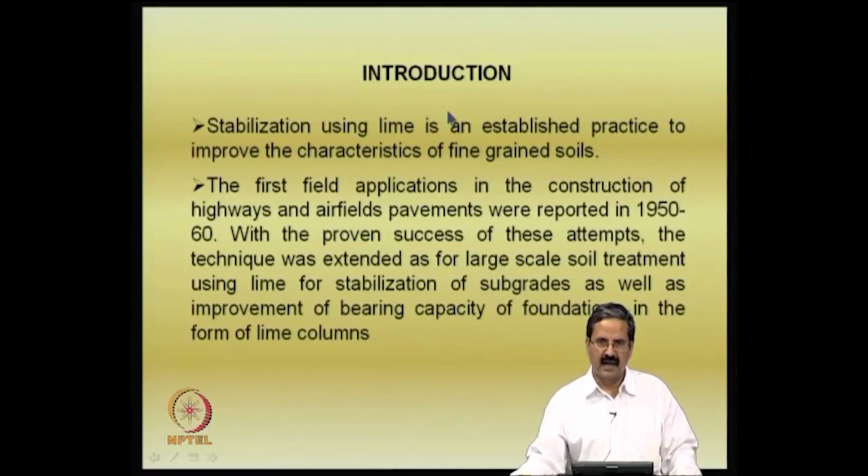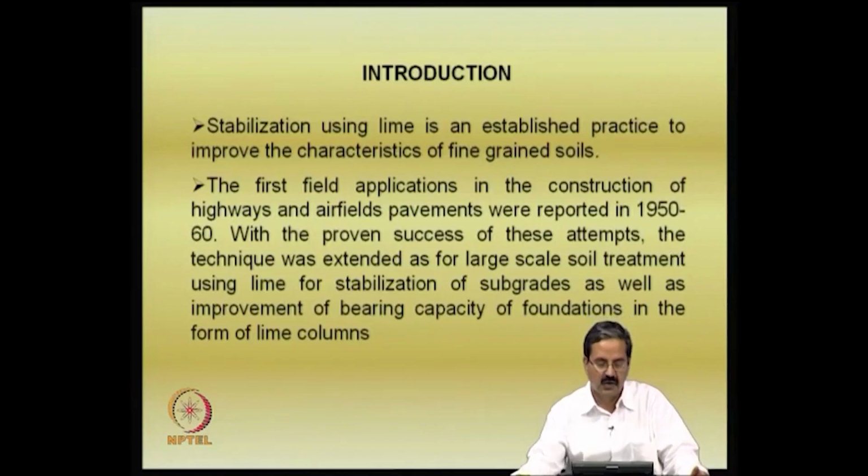Stabilization using lime is an established practice to improve the characteristics of fine grained soils. Actually, it has been quite effective in all fine grained soils, not necessarily expansive soils. If the soils are fine grained, which means they have high specific surface, whether because of certain ions present in the material or because of the water present in the materials, then the liquid limit and plasticity characteristics are reflected in higher values. The higher the liquid limit, the higher the specific surface. In treating particularly fine grained soils, lime treatment has been very effective.